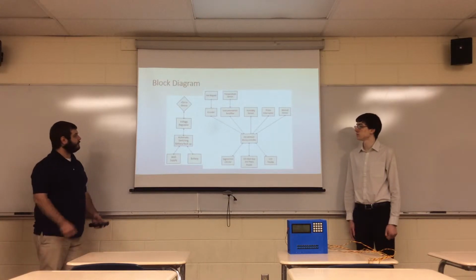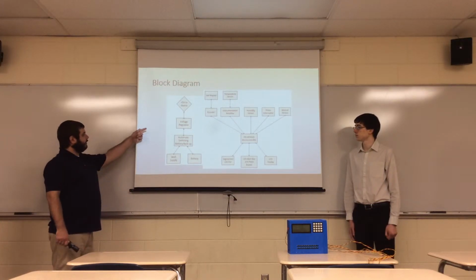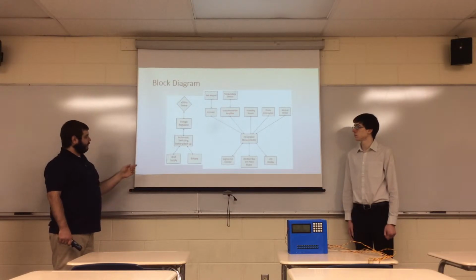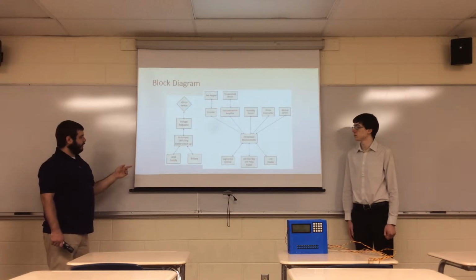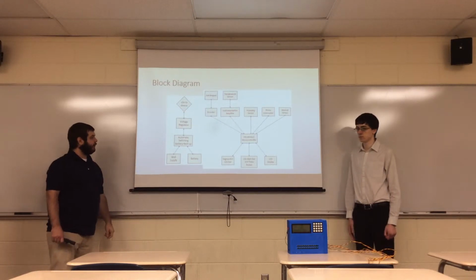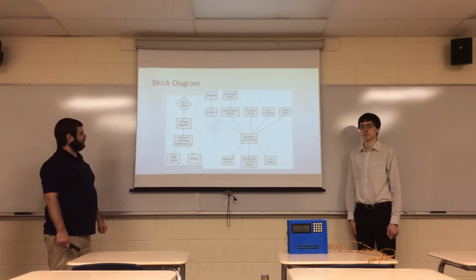Block diagram of the device. Our power circuit is, everything's powered by 5 volts. It comes from either the wall supply or the battery. We have an automatic switching supply that switches if we lose the wall supply, and goes to a voltage regulator to regulate it down to 5 volts.